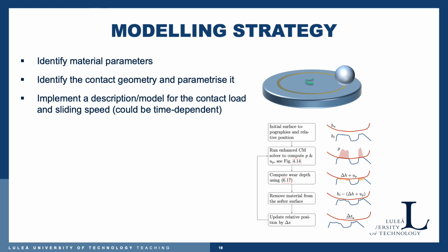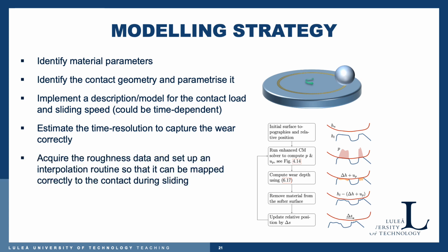We then implement some kind of model for the contact load and the sliding speed. It depends on what system we are simulating, of course. And we estimate the time resolution required to capture the wear correctly. As you saw, it was crucial to pick a small enough time step, but it's also crucial to pick a large enough time step so that we can actually perform the wear simulation in reasonable time.